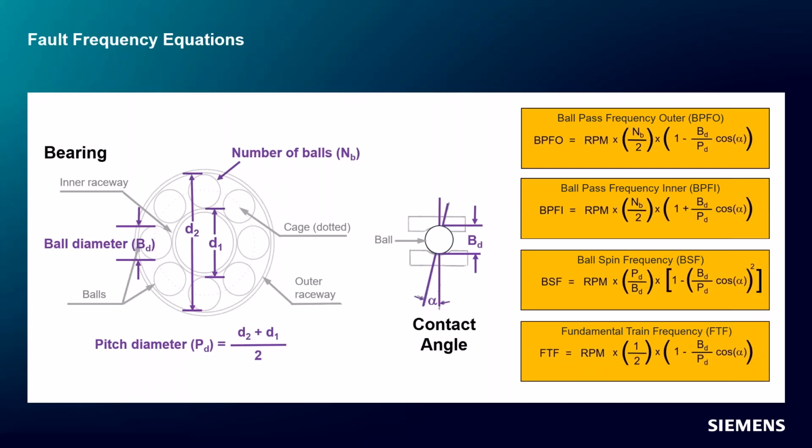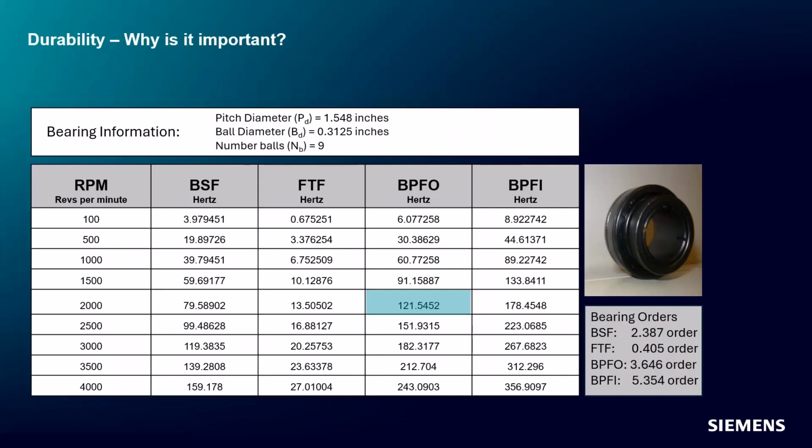Yes, I have. Like I said, we'll be doing an example here with this particular bearing, and we purposely induced a failure on it. So we measured it with and without a failure. We measured the vibration at the same location on the non-rotating part of the bearing with the fault present and without the fault present. And we purposely made a fault on the outer race of the bearing. The data we'll analyze is around 2000 RPM, and so we would expect the fault around 121 hertz, 120 hertz or so. Does that make sense so far?